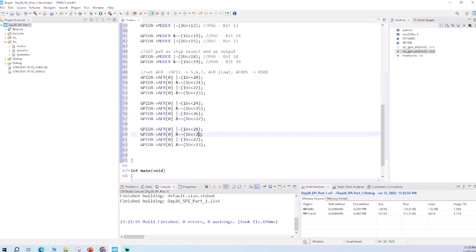As I know, it's a 32 bit. 29, so this will be 30, and this will be 31. Okay. So now we set the output data, so we don't need the GPIO 31. Okay, this is all the config we need.